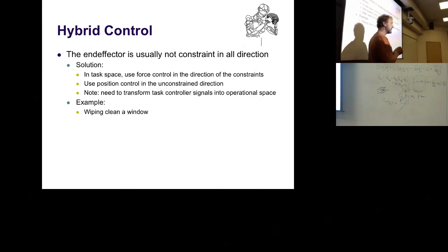All of you have seen Karate Kid. Wax on, wax off. That's a perfect task for hybrid control. Position control in the tangential plane, I hope, and force control in the vertical plane, in the normal direction.